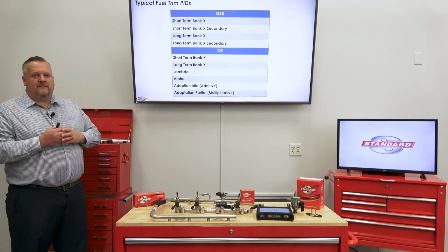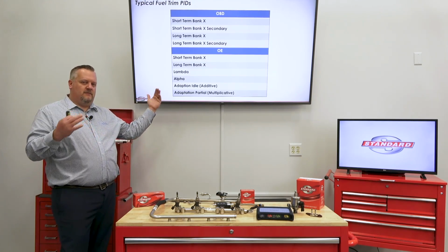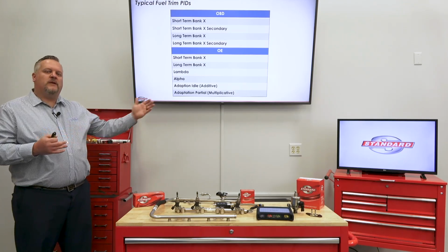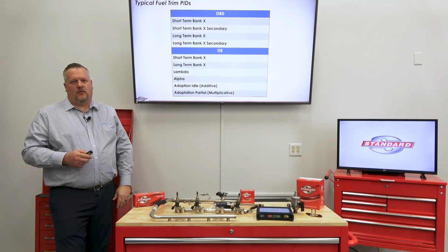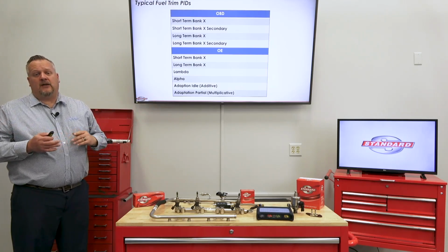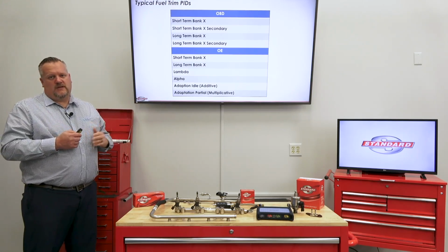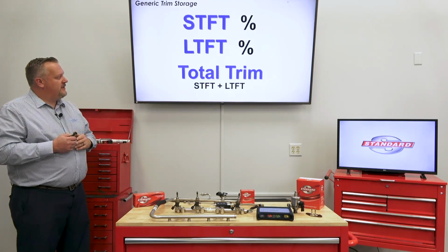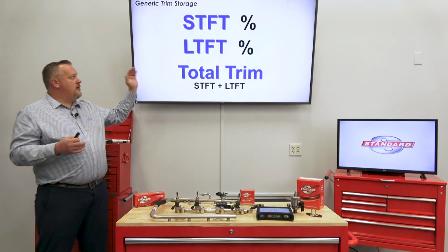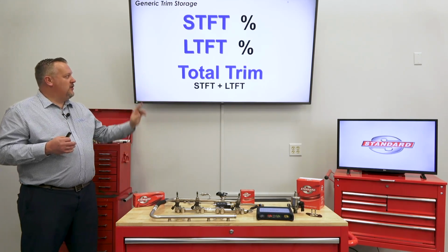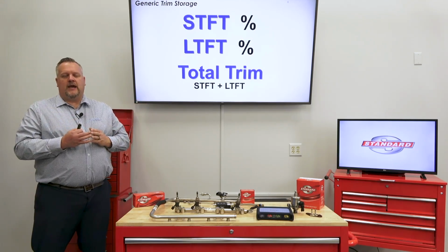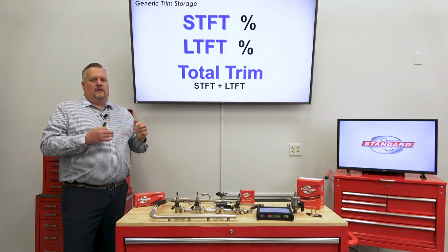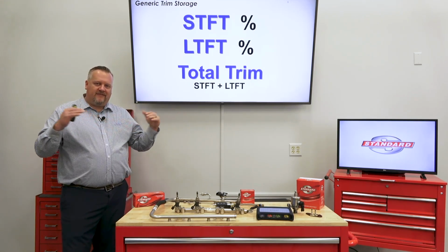We've got a lot of different terms here. Hopefully you've familiarized yourself with this, but don't be surprised if some of these additional terms show up on your scan tool at some point. And feel free to come back and refer to our presentation today to touch up on some of that. Remember, generically, we're adding our short-term and long-term to come up with our total term, and we want to actually look at the recorded or graphed data here.